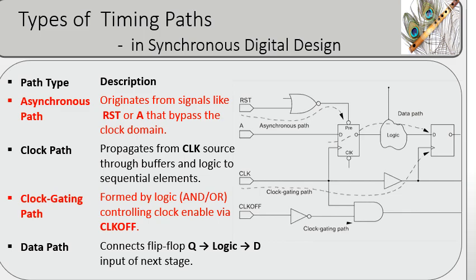The clock period determines the required arrival time. The data path is the actual path that transfers data between input and output pins, passing through sequential and combinational logic gates. The path elements' delays determine the actual arrival time. Therefore, data propagation time along with the corresponding clock period determines the timing path performance.